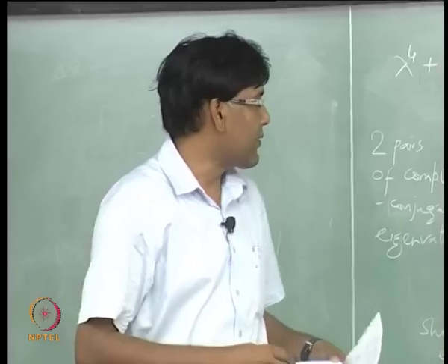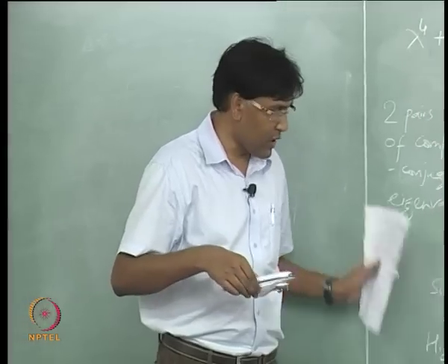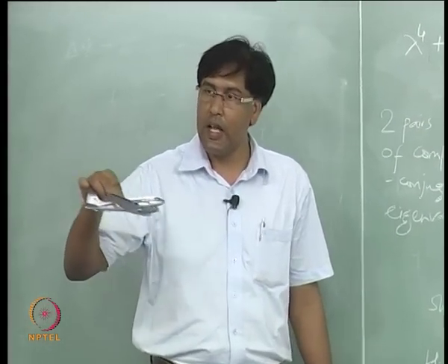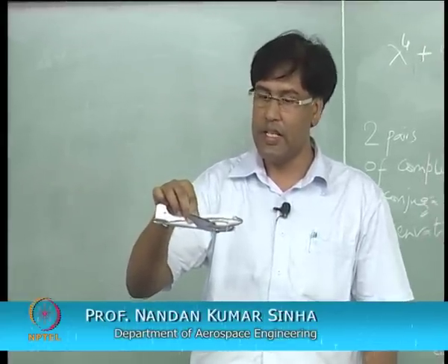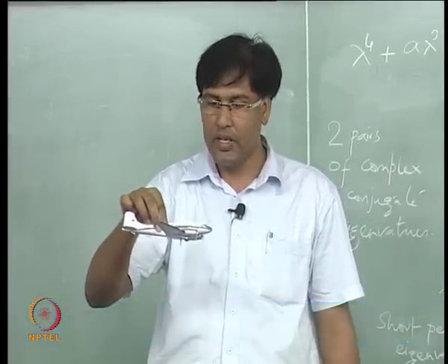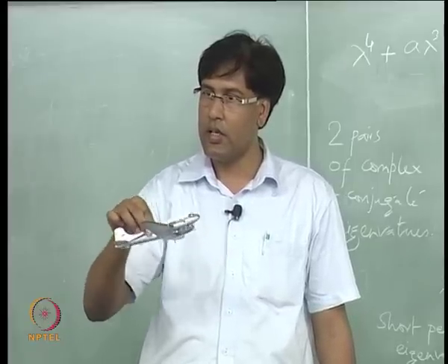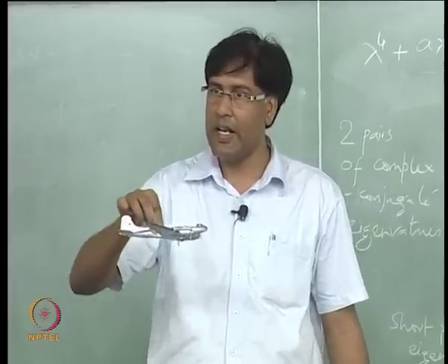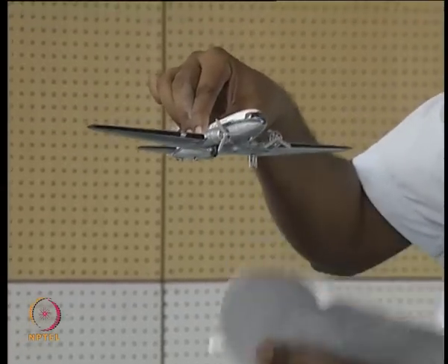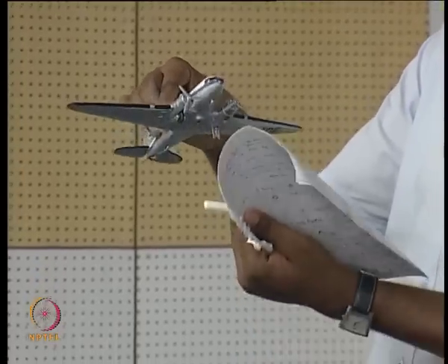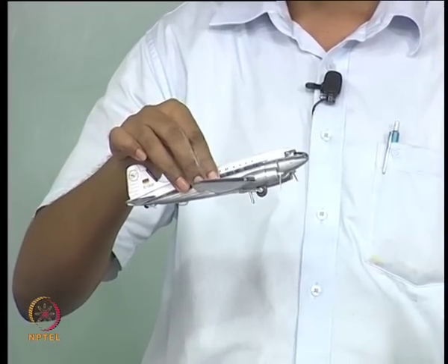And they found that the short period motion, if you look at the equilibrium flying condition where the aircraft is going with constant velocity and there is a perturbation, is a very fast pitching motion and highly damped. So, it will damp very fast. When a disturbance hits the aircraft, it starts doing this motion which damps out fast.